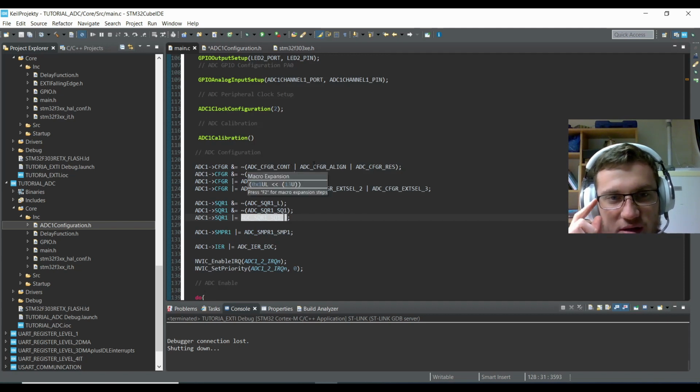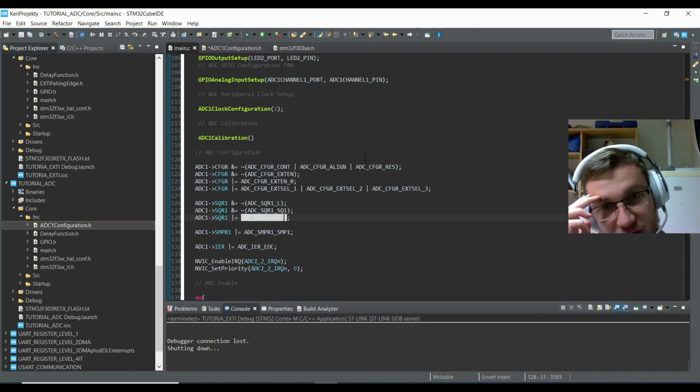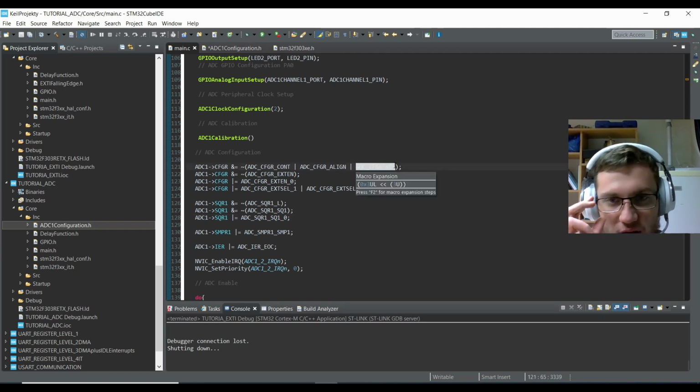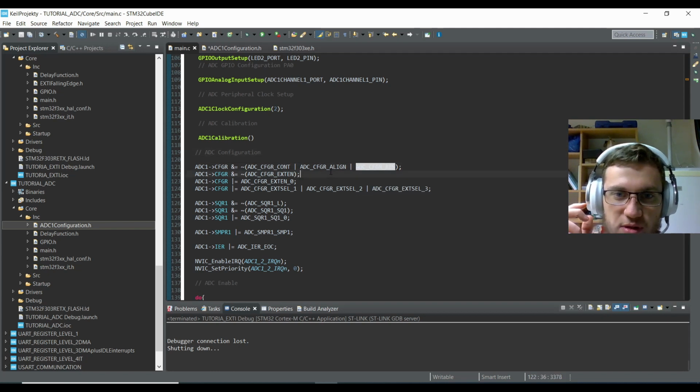As I am looking at it, basically this is like 80 or 90% of the times when I use ADC, I use it this way. So I'm using some sort of timer as a trigger. I never usually use continuous conversion mode. I use 12-bit resolution because that's one of the reasons why I moved to STM32 controllers anyway.